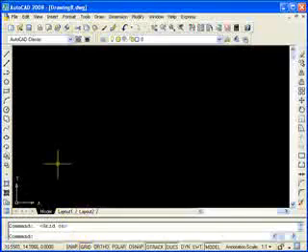And remember, my grid fills the extents of my limits, which we talked about in tutorial number 9, setting our drawing limits. Our grid extends to our drawing limits. You might not be able to see it, but my grid is showing up right down here in the bottom left-hand corner of my screen, which is telling me that's what my drawing limits are set to, somewhere over here.